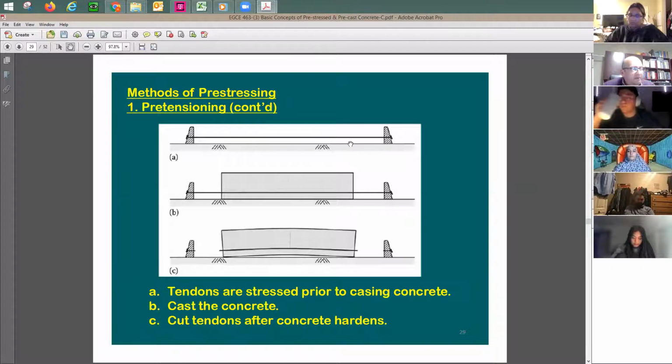Now, this is here under tension, and this strand here is also under tension. When you cast the concrete, this concrete here is not stressed yet. Why? Because the tension goes to the abutment. So this rebar here, or the strand, is kind of stretched. You increase the length of it. When you apply tension to it, the length got increased; let's say the original length was L, now we are adding delta L to it. So now it has some tension in there.